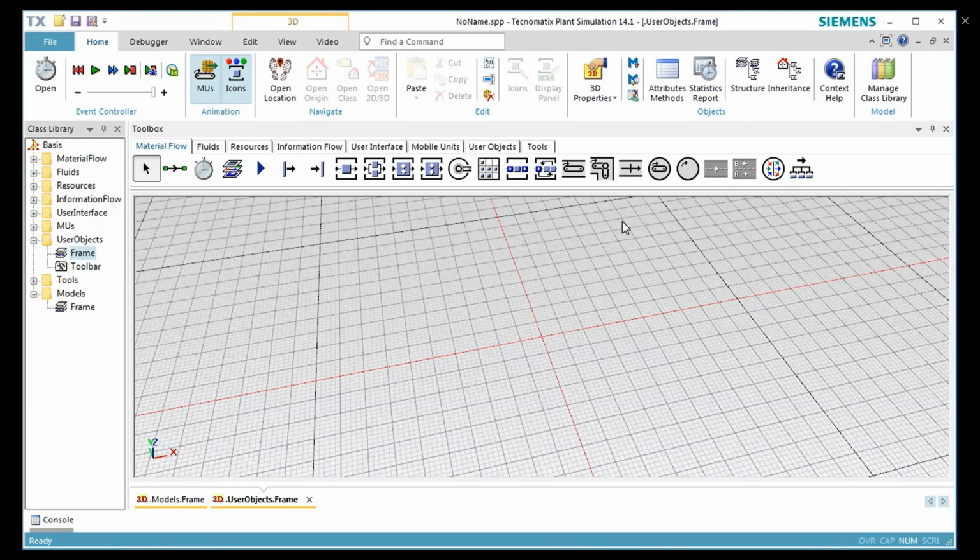In the first step, the drilling head has to move down and stop above the product. In the second step, the drilling head has to rotate and move slowly down until the hole is drilled. The time for drilling depends on the thickness of the object. In the third step, the drilling head moves up slowly and continues to rotate. In the fourth and final step, the drilling head moves up fast to its default position.